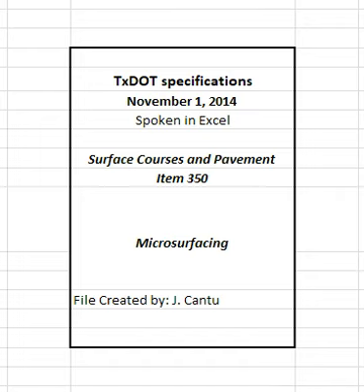Weigh the aggregate at the project stockpile site unless otherwise approved. Use either a suspended hopper scale or a belt scale meeting the requirements of item 520, weighing and measuring equipment. The calculated weight of mineral filler based on the accepted portion of work will be used for measurement and included in the total aggregate weight.